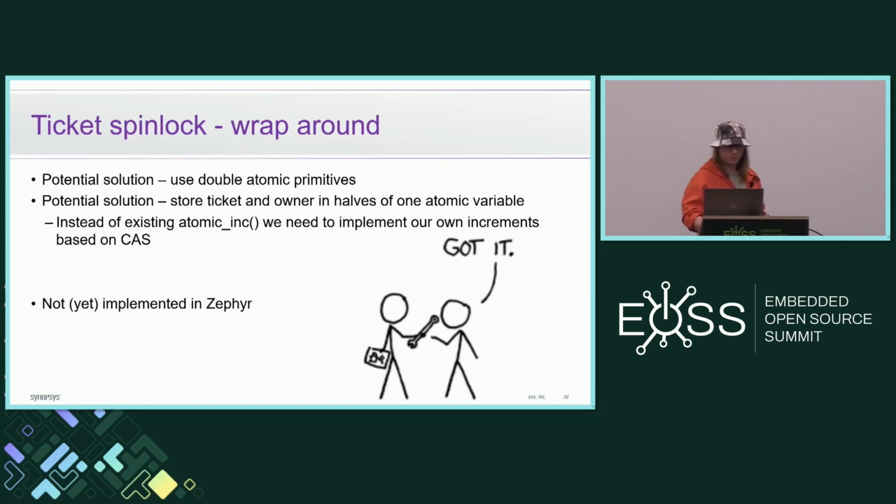I think there is actually another question from that person. I don't really understand if a true SMP system could be implemented with such a memory approach, because if there is no coherency between cores, how could that even be possible? That question makes no sense, because everything in that presentation relates to SMP systems only. In an AMP system, there would be another way of synchronization, and on a single core system, there is no problem at all. So it is kind of a question taken out of context.